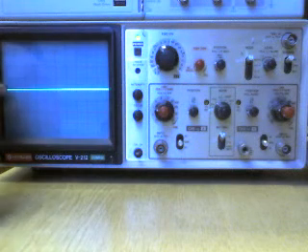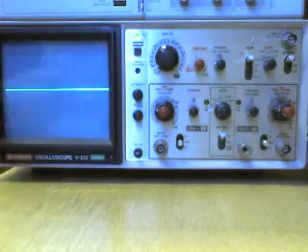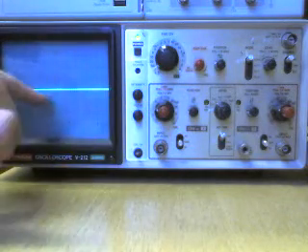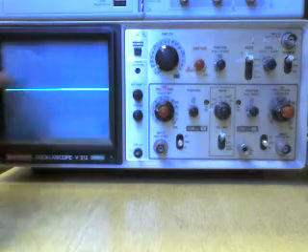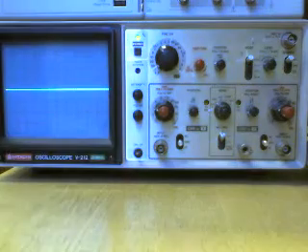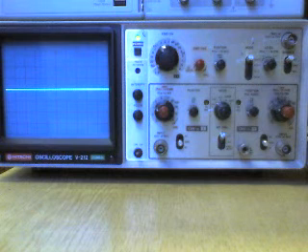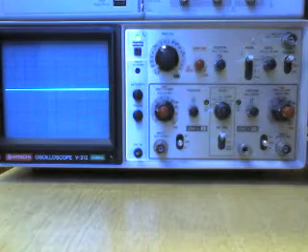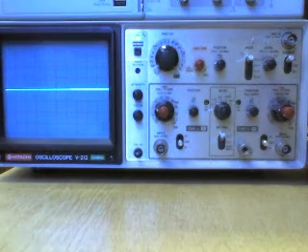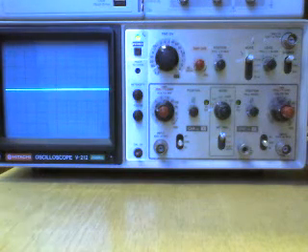It starts on this side of the oscilloscope, and it's 1 millisecond per division going right across the oscilloscope. 1, 2, 3, 4, 5, 6, 7, 8, 9, 10. You can measure the signal up to 10 milliseconds. So if the signal has a period of less than 10 milliseconds, I would see multiple cycles on the screen. If it's got a period of 10 milliseconds, I'd see just 1 cycle on the screen. So on. It's pretty simple.